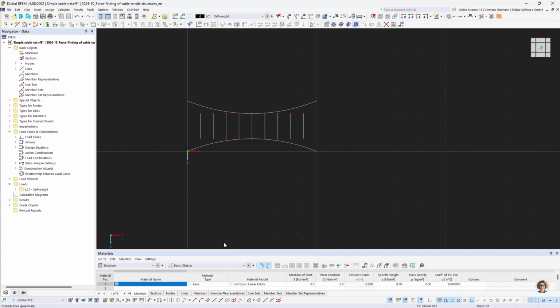So if I click on it and hover over the end of a line, it automatically searches for other lines in that plane and creates a preview where an intersection has been found. And if you click on it, the intersection is made and the line is extended to the other line. And that way, complex intersections can be made quite easily and fast.